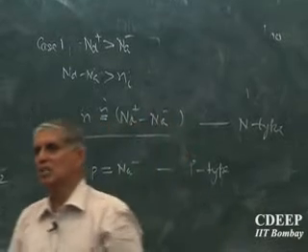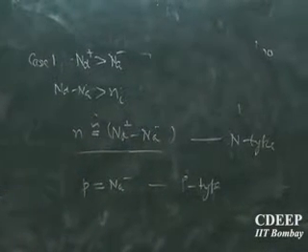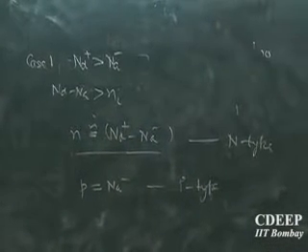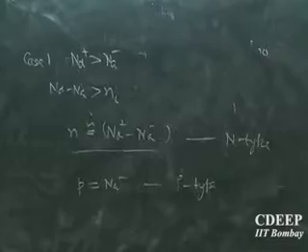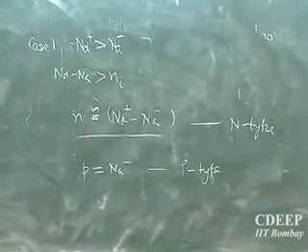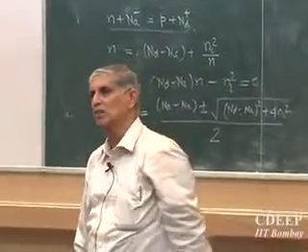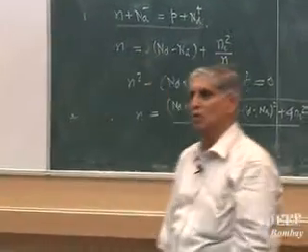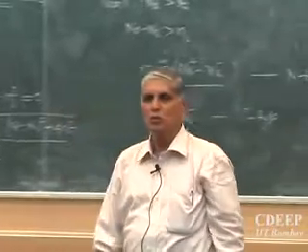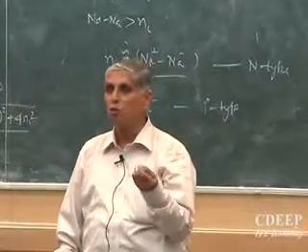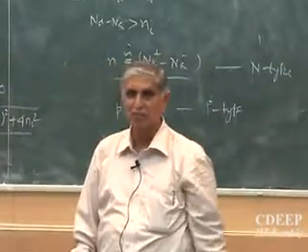So the hole concentration is almost equal to the acceptor concentration, in case the concentration of acceptors is larger than N as well as Ni. When we say almost all holes will be available for transport, as many as there are acceptors. So in technology, we actually decide how many impurities are in.